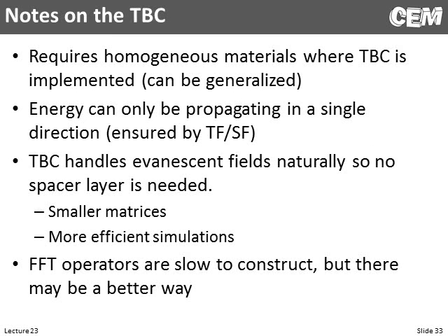Okay, so instead of using a PML, which requires the use of, let's say, 20 cells plus even a spacer region, that's a lot of real estate in a three-dimensional grid. There's another type of boundary condition that I'm calling a transparent boundary condition that we can use. In other packages, sometimes they may call it the Floquet boundary condition, but we can do this in one layer and it works perfectly. It handles evanescent fields, so we don't need the spacer regions, and it just works really, really well.